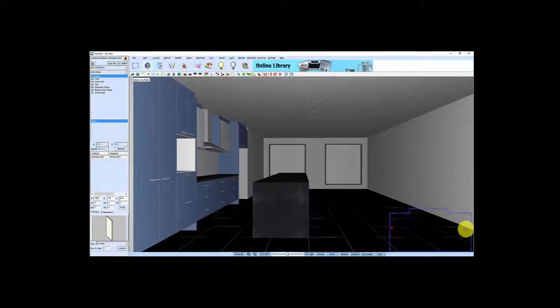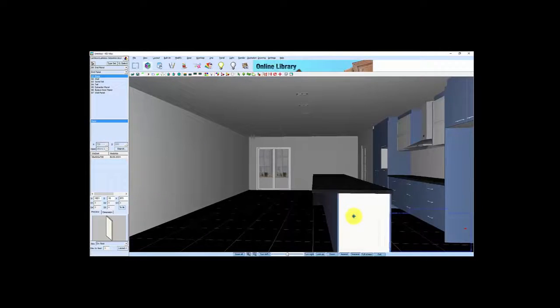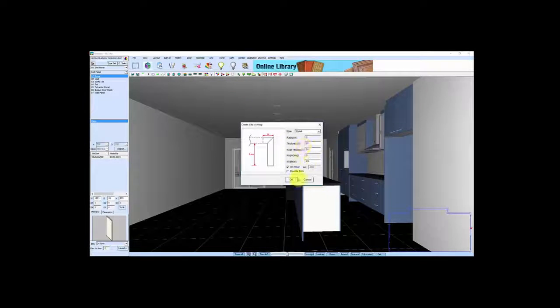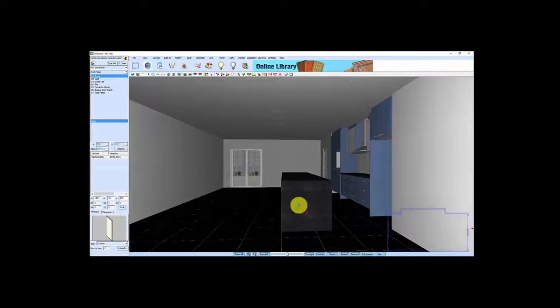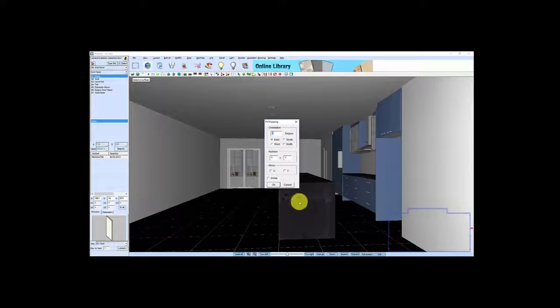What I want to do now is go to the opposite end, and I want to do the same on that section there. So we go to worktop, create side worktop, select my edge, go OK. Okay, then I want to do the same with that. I want to go to render, just go to fit map, select that, go right click. We go OK.